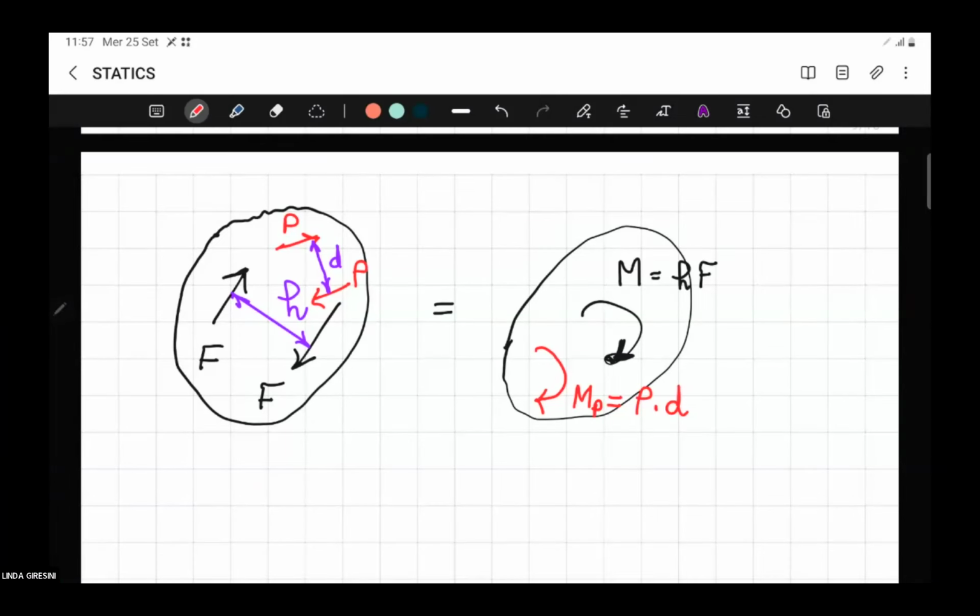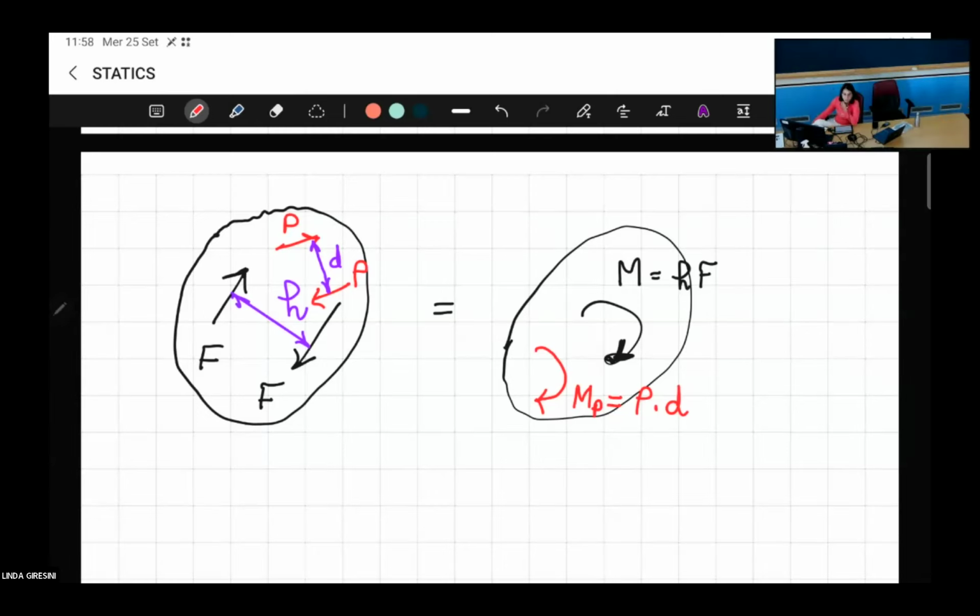Is it like a beam or something like that? Yes, you can have a beam, for example, where two moments are applied to couples. Yes, even more. I mean, there is no limit. Generally, the moments, the couples are seen applied to points, to specific points. But for beams, the issue is different. Because for beams, you don't have rigid bodies. So you can translate moments only for rigid bodies. For deformable bodies such as beams, you cannot do that.